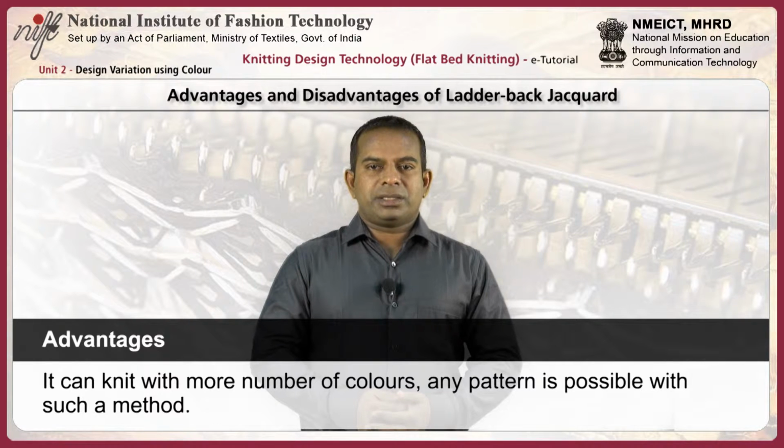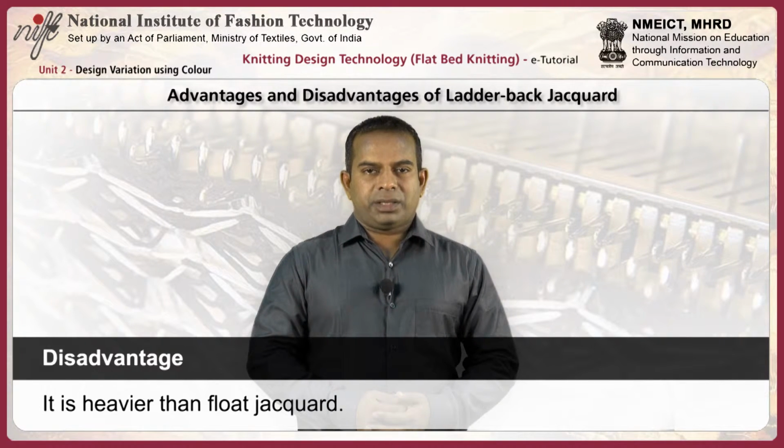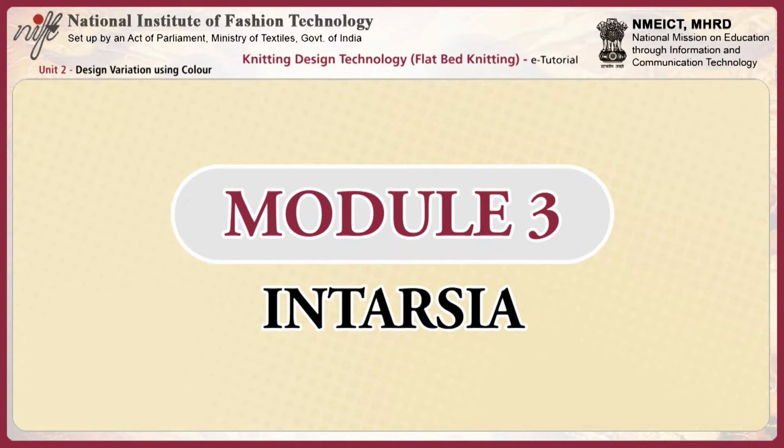Advantages. It can knit with more number of colors. Any pattern is possible with this method. It is lightweight compared to bird's eye jacquard. Disadvantages. It is heavier than float jacquard. This module focuses on intarsia.